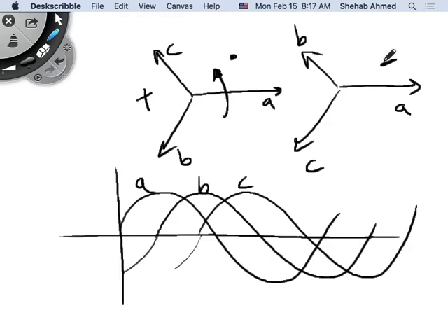In a star-star and a delta-delta transformer, if I choose my ratio of the bases equal to the ratio of the terminal voltages, then I don't have a problem. The transformer will be eliminated. It will be a one-to-one transformer. Anytime you have a star-delta or a delta-star transformer, meaning a transformer that phase shifts the quantities on the primary with respect to the quantities on the secondary, you cannot eliminate the transformer. You can eliminate the transformer's turns ratio by the same choice of base ratios.